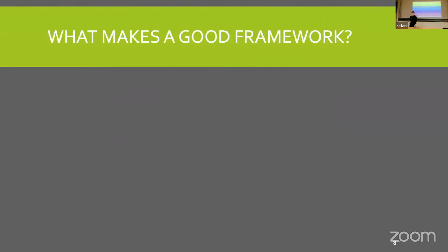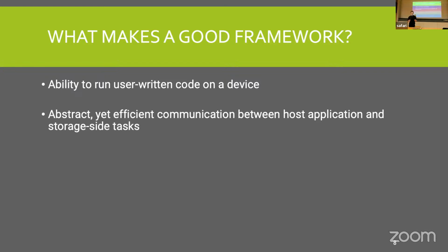So, Biscuit. Before talking about Biscuit specifically, let's talk about what makes a good framework in general. The paper provided a couple of key points. One is the ability to run user-written code on a device, which is quite obvious. That's the entire point of the framework. It should also provide an abstract and efficient communication between the host application and the storage side tasks, so the tasks that run via near data processing. This is really important such that the user doesn't have to deal with the low-level firmware of the SSD or the communication, which can be quite complex if you're not experienced in that field.